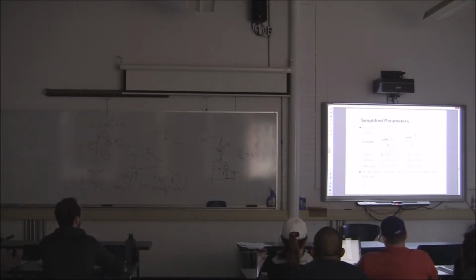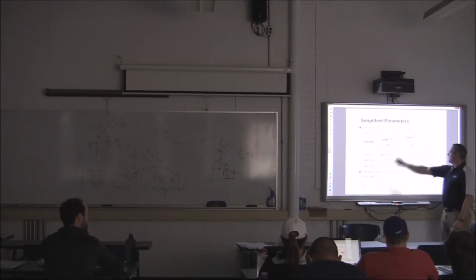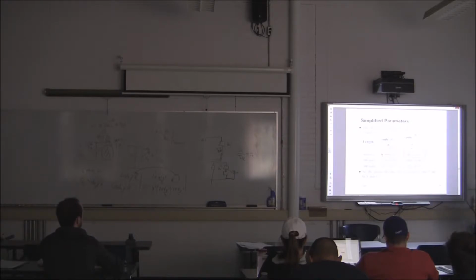Nada. Not for z, because the sine hyperbolic gamma L over gamma L doesn't change the magnitude or the phase shift, as does that one. That's essentially 1 at an angle of 0 as well. So for a short line, what do we do?